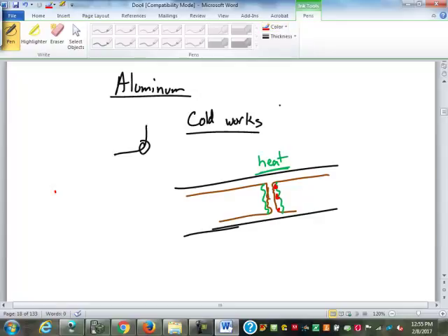I've seen them in a stud wall actually cut a groove. They've got a saw that's made to cut a groove, because the wire has to be at least an inch away from the surface of the stud. So the saw has a 1.5 inch depth, so it cuts through a 1/2 inch of sheetrock and then an inch into the stud, and it's 5/8 of an inch wide. They cut that groove right through the wall so you can stick new wire in that groove and then fill it with sheetrock mud, patch it over.